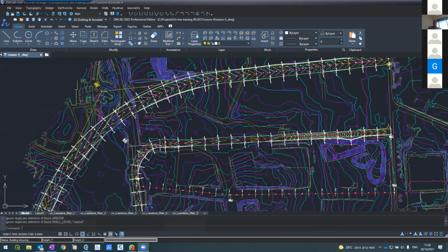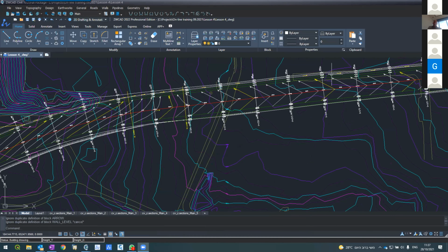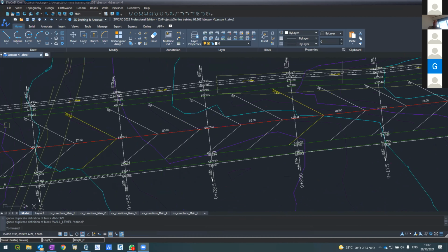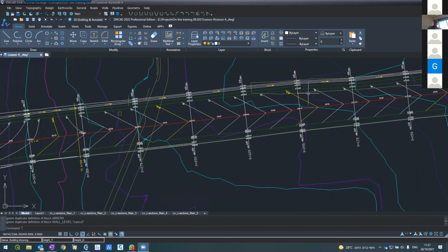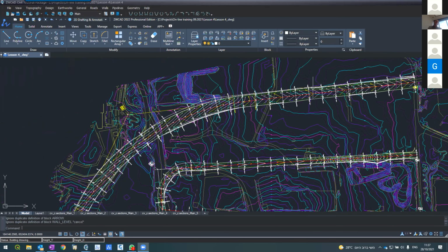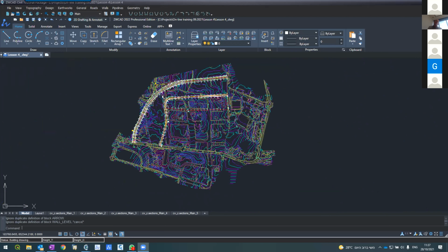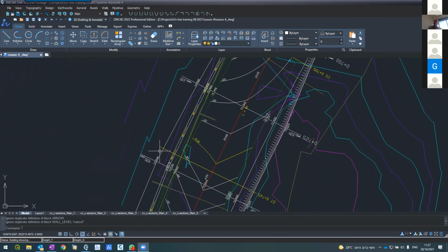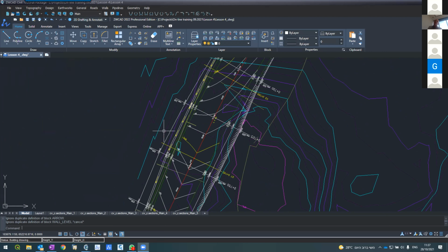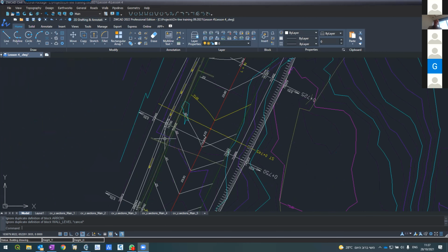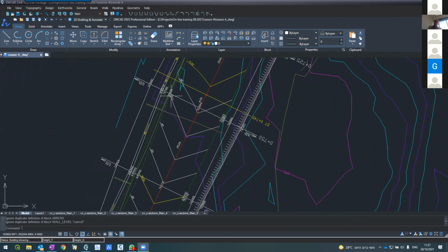Excellent. So now what I've done, from here, I've widened my road from right lane from 7.3 to 9.3 and changed it back at 750. 750 is here, see? From here, it's going back, from here going back to here, 9.3 to 7.